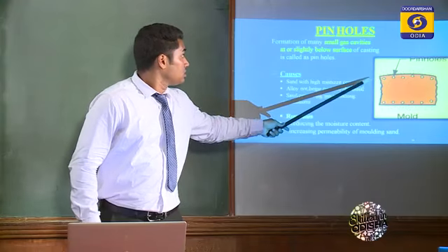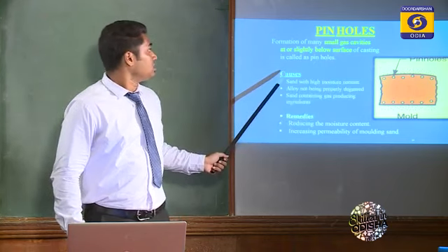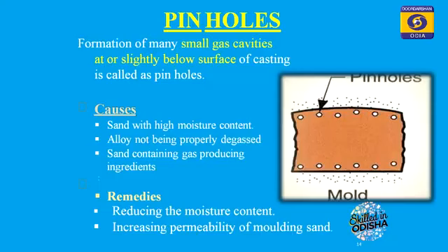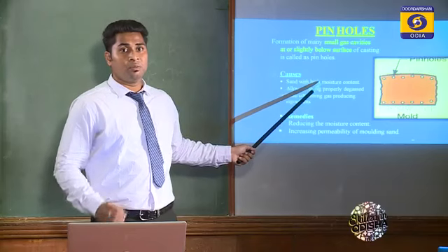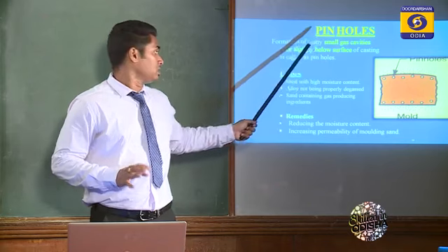Okay, you can see what the reasons for these pinholes are. First one is sand with high moisture content. This is the main important reason for the pinholes defect.